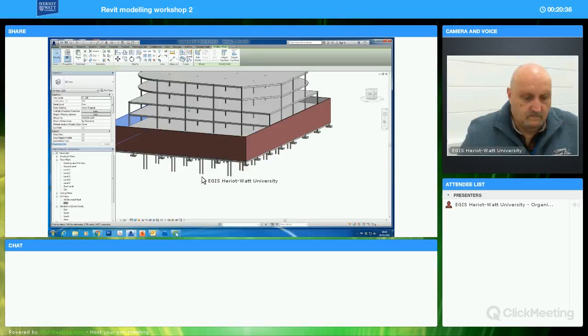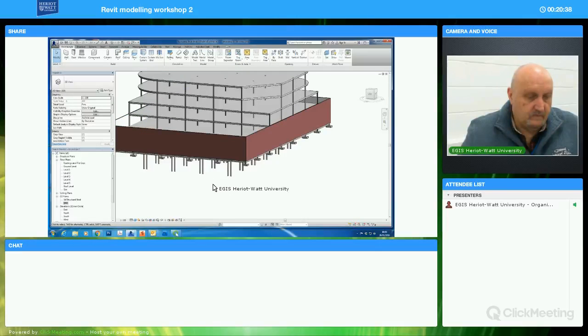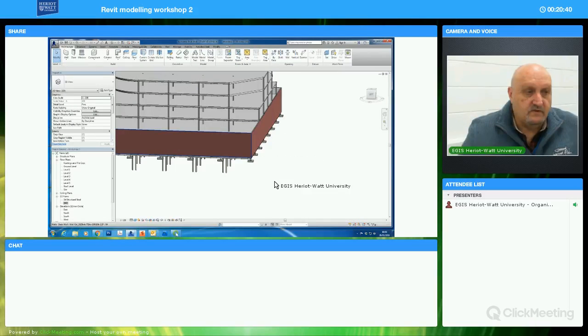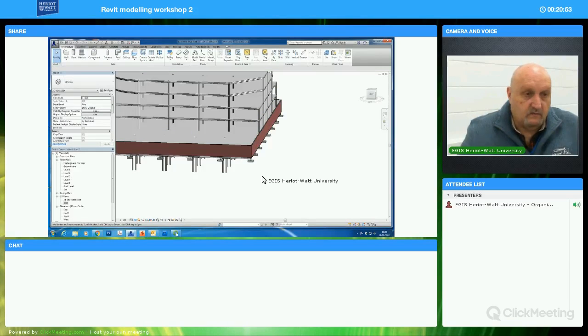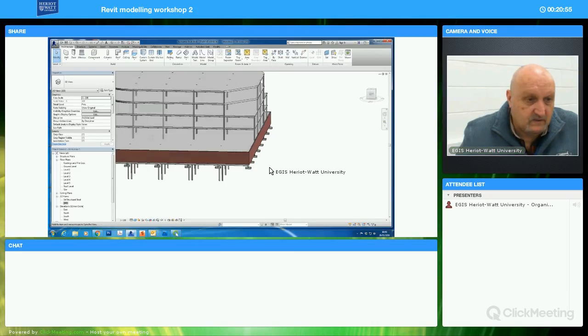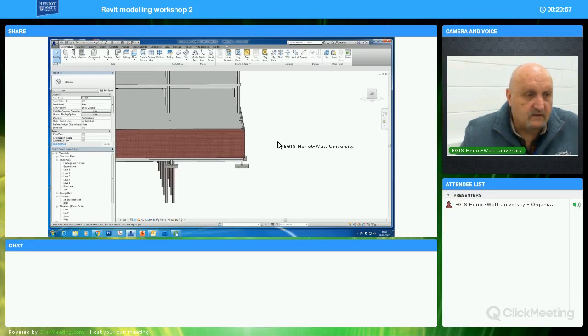And that one there, bricks on the inside. And then I can select all these walls by SA and make them go from the base constraint ground level, which is right, but the top constraint is just to be up to level 1. I just want these walls to go to level 1. Now, I want you to pay attention to this wee bit here,